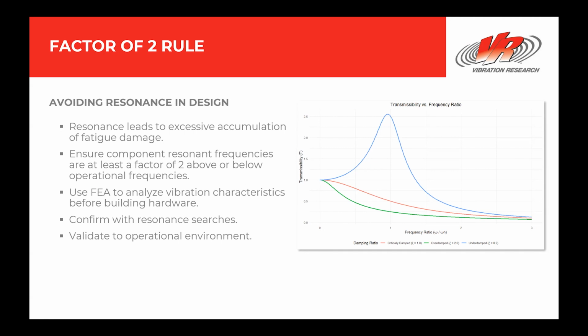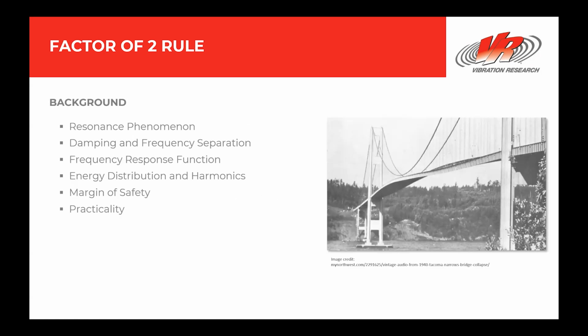Vibration Research has many tools available to perform resonance searches and to validate analytical models. These analyses and confirmations are very important, not only for the product itself, but also for any test fixtures that will be used for vibration testing. A vibration test fixture that imparts undesired resonant energy into a product leads to ambiguous test results and must be avoided. Once the design is finalized and analytical models confirmed, it's time to test production intent parts with a representative vibration profile. Let's talk a little bit more about resonance.